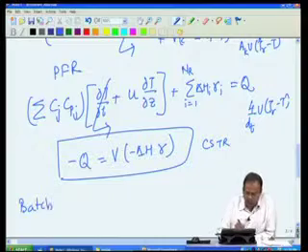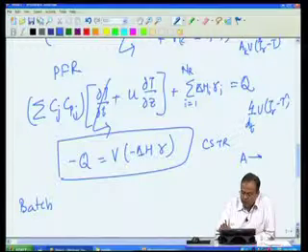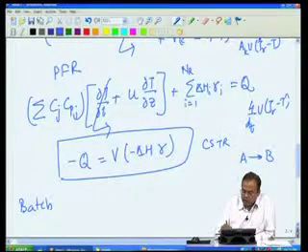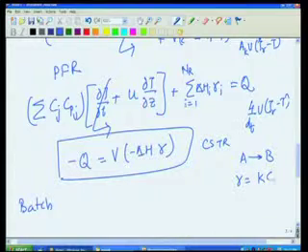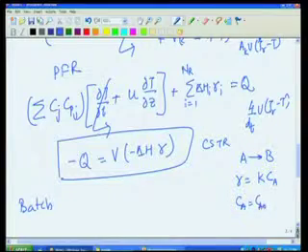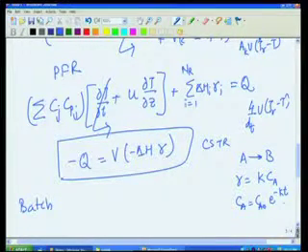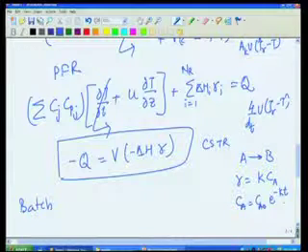What is it that is required in a batch reactor now? For a batch reactor, I am just going to assume a first order reaction. Let us say we have reaction A going to B, the rate of this reaction is k into Ca, where k is a function of temperature, and we are going to use isothermal. So, we know my concentration changes from my initial concentration in an exponential manner.